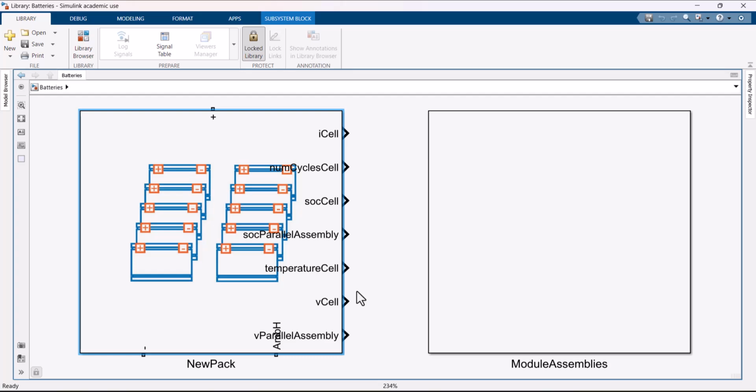Hence in this tutorial we designed a battery pack step by step using the MATLAB Battery Builder app, starting from a single cell and reaching a complete pack with 14.8 volt and 81 Ah capacity. In upcoming videos we will explore thermal modeling, pack performance under different loads, and integration with power converters, etc.